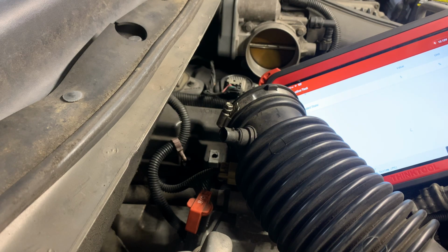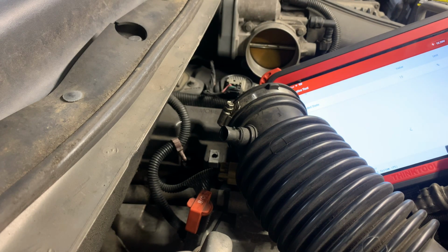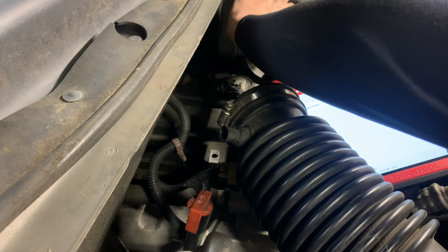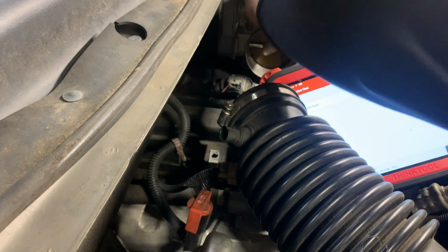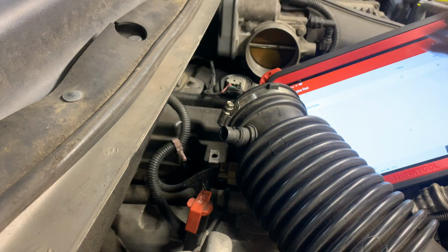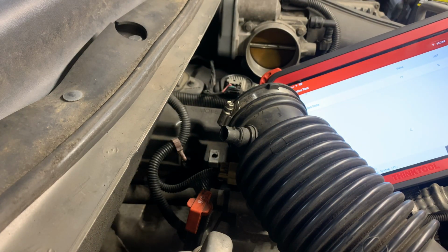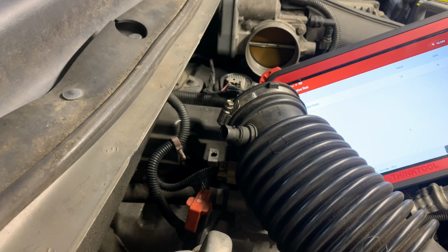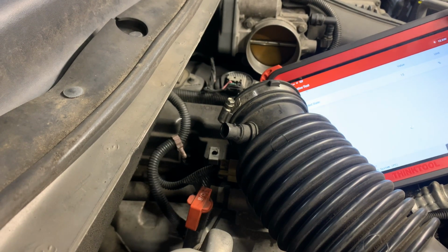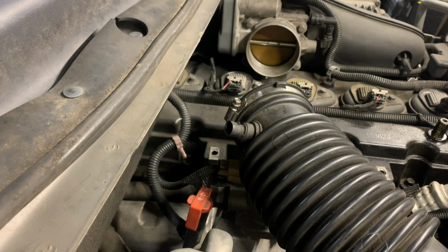So now I get out of the vehicle and I actually set the camera down, and I go in and actuate the throttle. No, I think I'm doing it from the scan tool right here. I'm just out of the shot. You can't see my fingers, but there's a way to control it. And it acts like this throttle body is binding up. I'm looking at that now, and I'm starting to think, well, now this throttle body, which is the original, doesn't seem to be acting right.